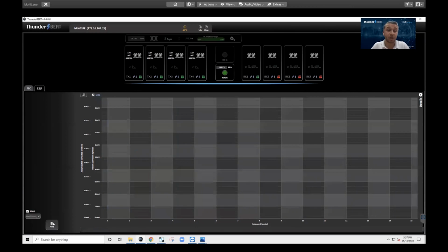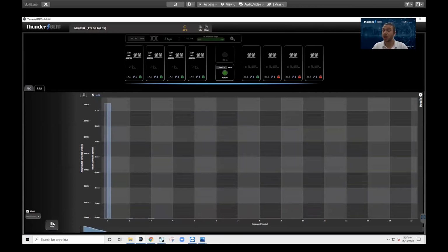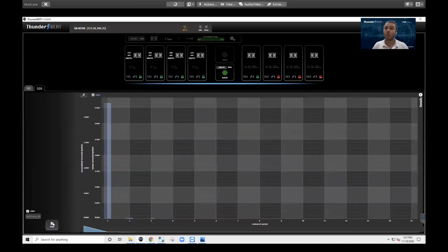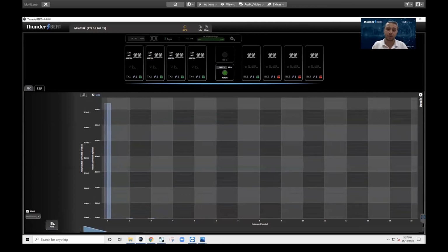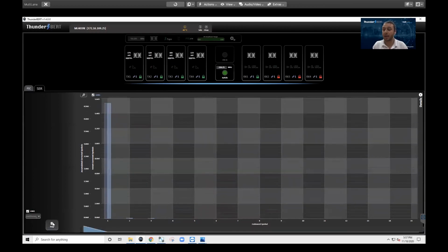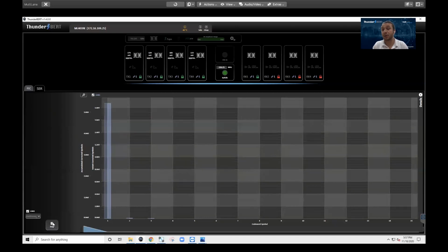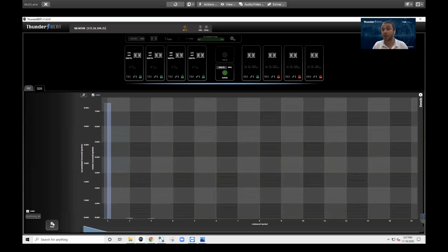So now I'm going to start that symbol error test to see really what is the margin of my FEC performance. In other words, how many more errors or how many more error bursts can I withstand with this setup before I break that 15 symbol error threshold and start creating uncorrected code words.